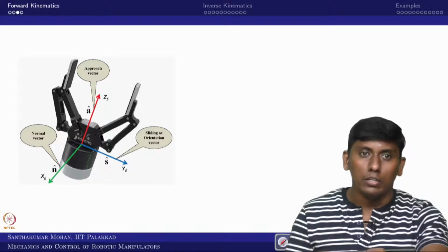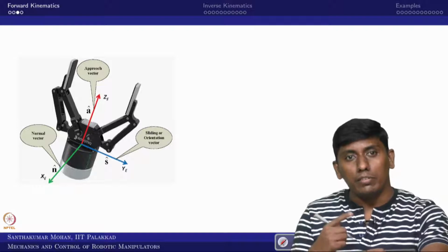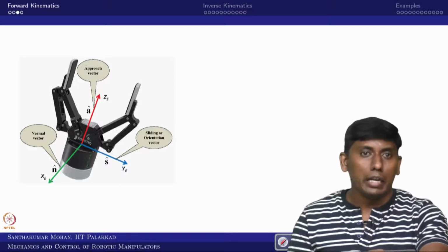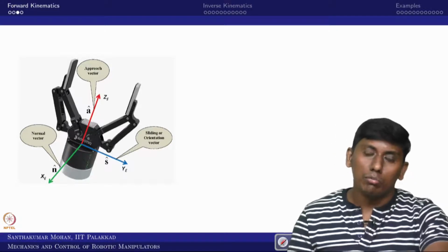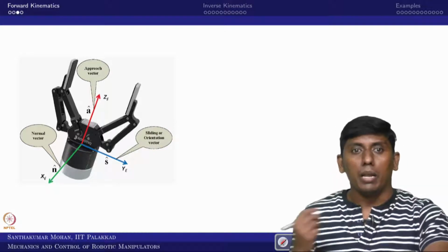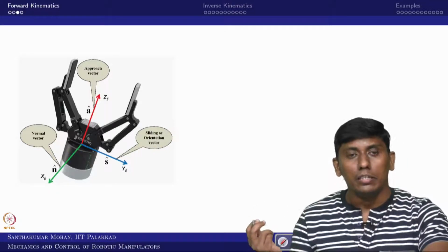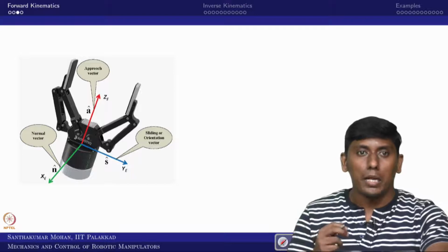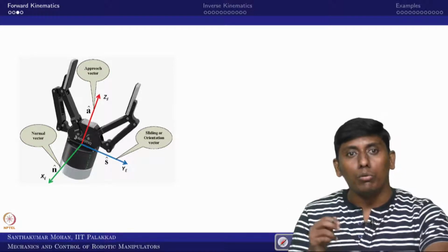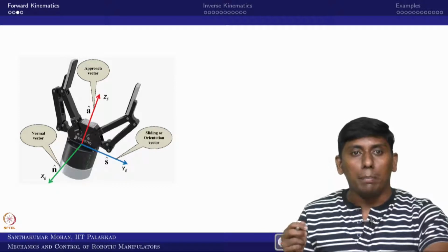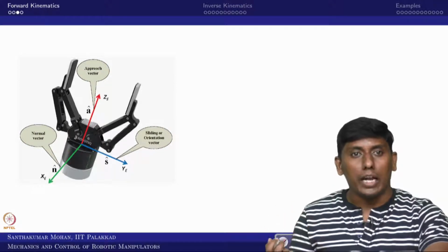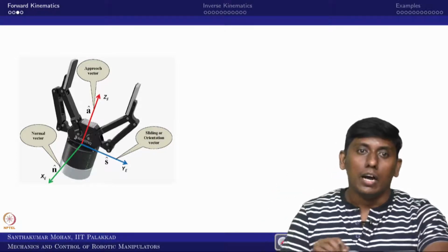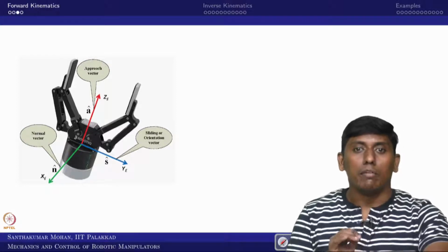We will go further on. Now you can see we have seen a few examples. We did not bother about the end effector, and we did not even fix the final end point in a certain format. So what would be the difficulty? I make a frame arrangement and end up with something, and you make another one and get something different. Both, the DH parameters and the transformation matrix, will give a right result. But when we transfer the information from one to another, we have to say this is the convention I have taken, this is the end effector convention, and this is the base coordinate I have taken.